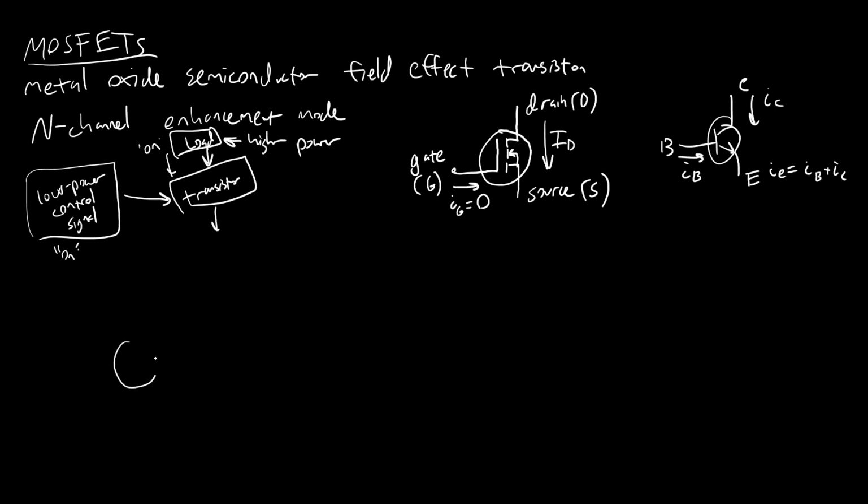So when connected to a microcontroller and a load, like we saw in the previous video for the BJT, the circuit is going to look something like this, where we are going to tie the source to ground. The drain is going to be connected to our load, which then may go up to some higher power supply. With a MOSFET, you might see it labeled VDD instead of VCC. So there is our load resistor RL.